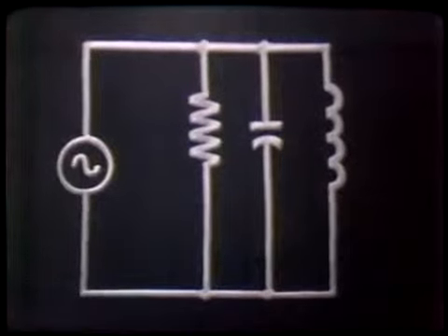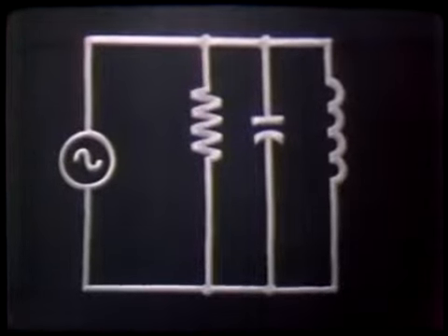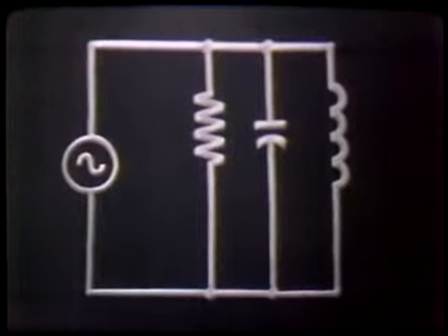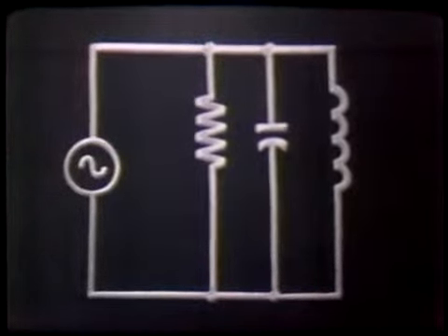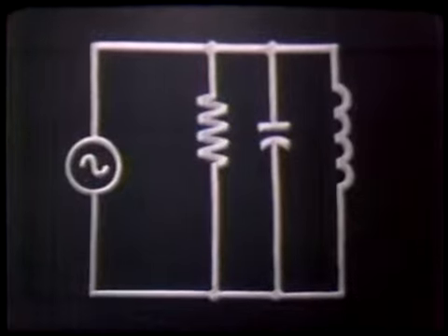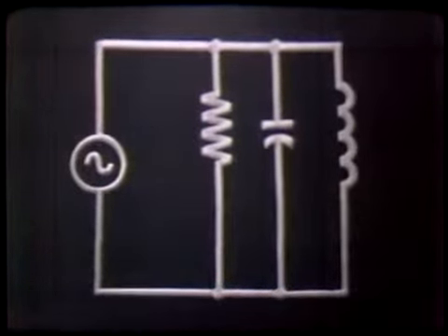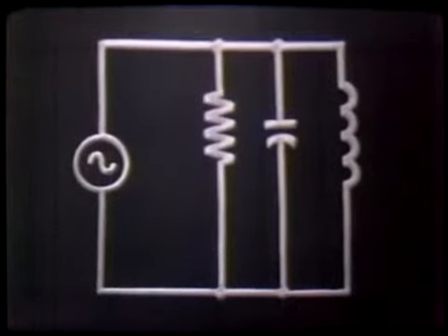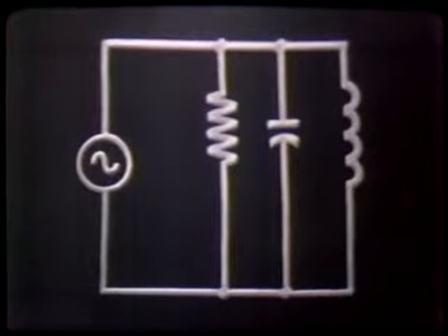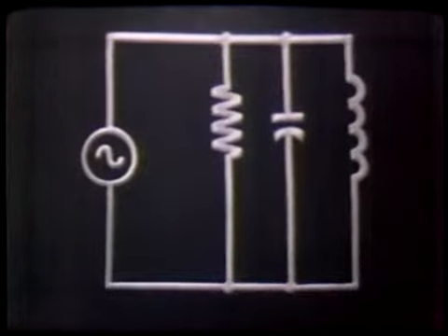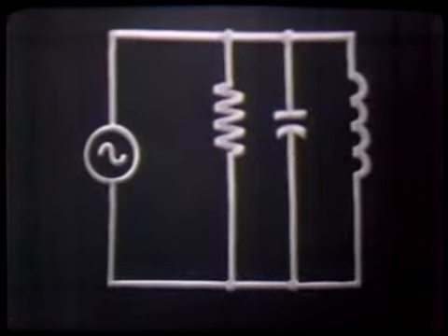Consequently, with the same voltage across each component, we only have one voltage existing within the circuit. Looking at the circuit with respect to voltage, it appears circuit analysis associated with a parallel RCL network is somewhat easier. In some respects, I suppose this is true, for in this circuit, the only vector we have to concern ourselves with is the current vector.